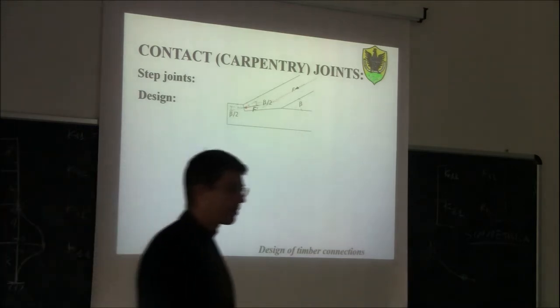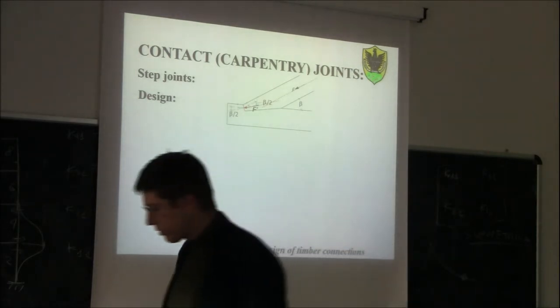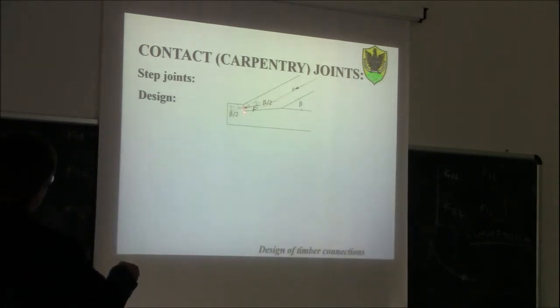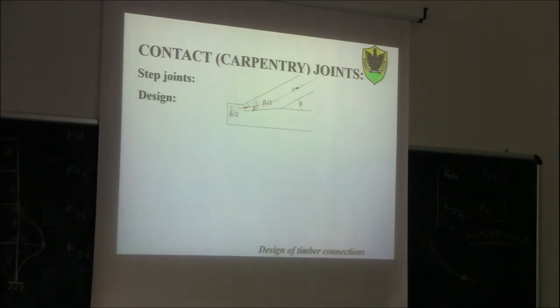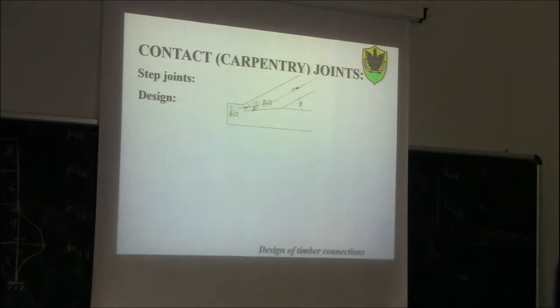So, how do we solve the problem? First of all, we have to decompose the force applied along the rafter into the different directions, assuming that this force will act perpendicular to the carving surfaces. So perpendicular to this notch, perpendicular to the other notch. Okay? And if we assume that this is a pin connection, how should the other two components be? First of all, of course, they should be in equilibrium.